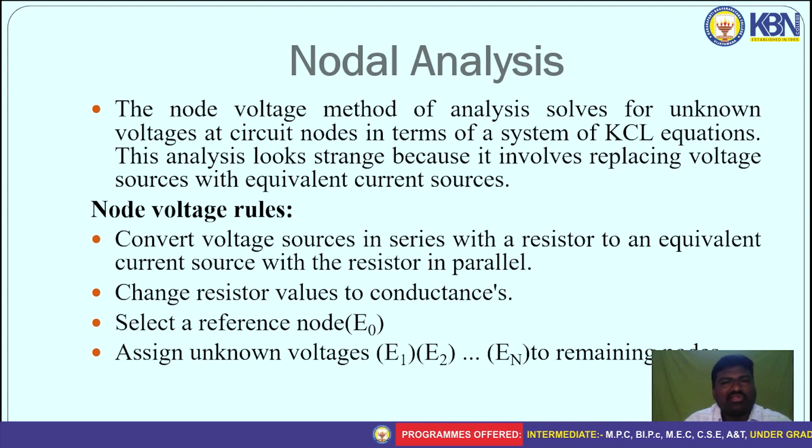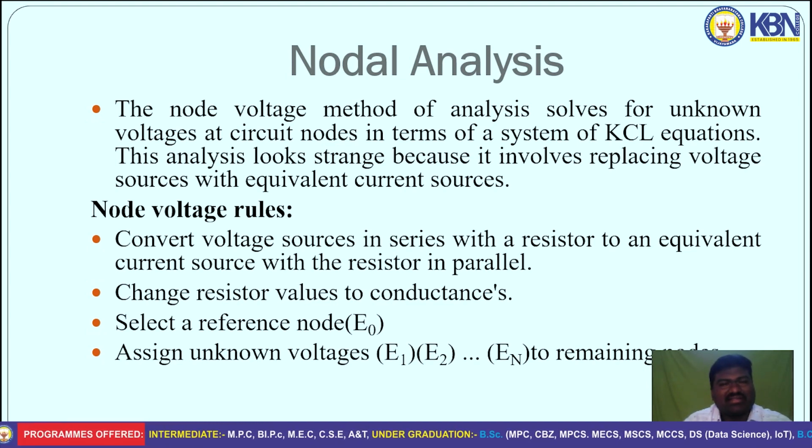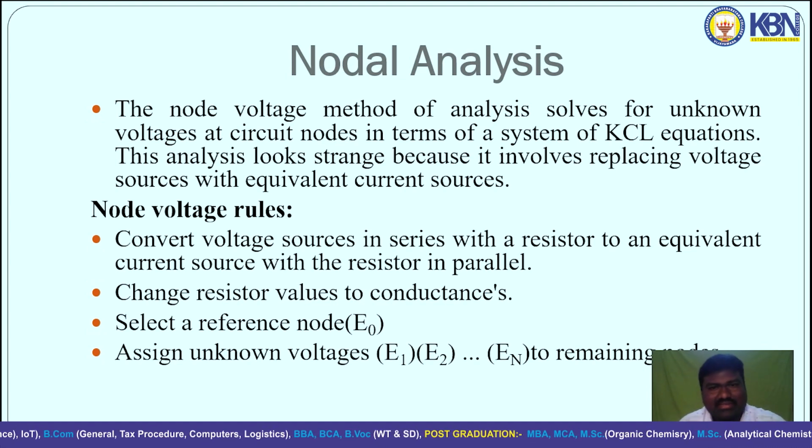The node voltage method of analysis solves for the unknown voltages at circuit nodes in terms of a system of KCL equations. This analysis looks strange because it involves replacing voltage sources with equivalent current sources.